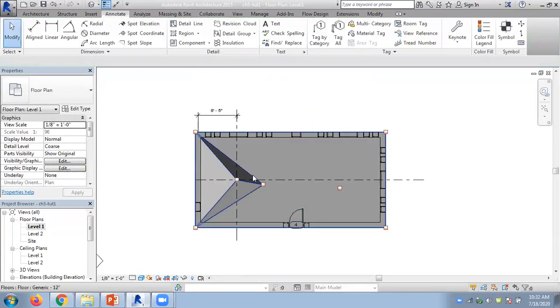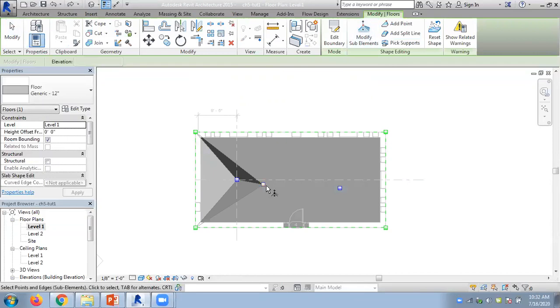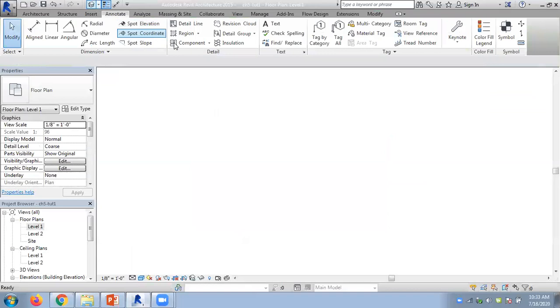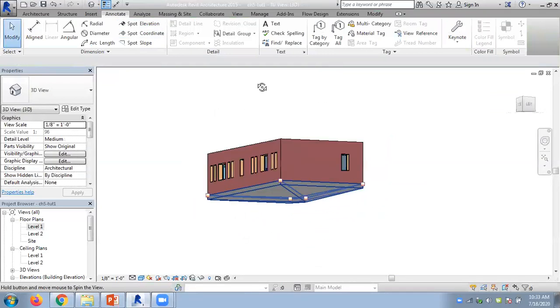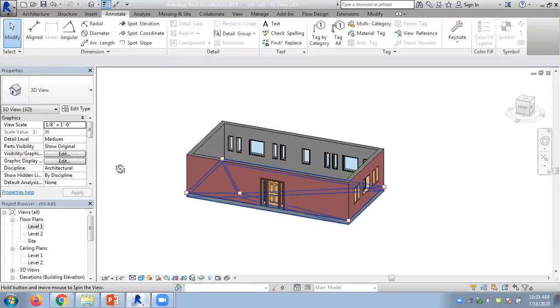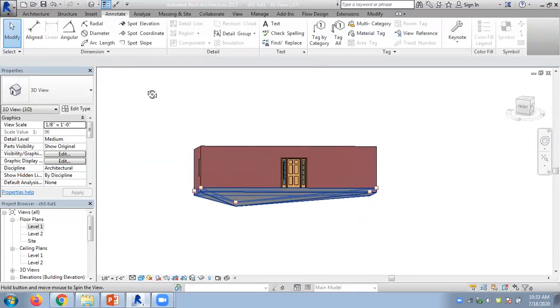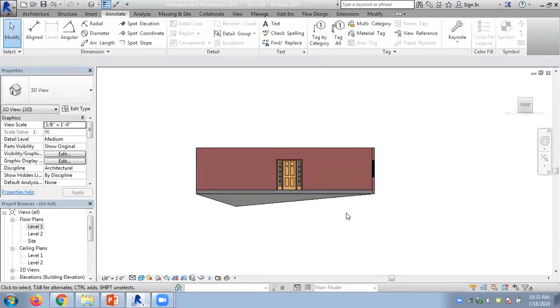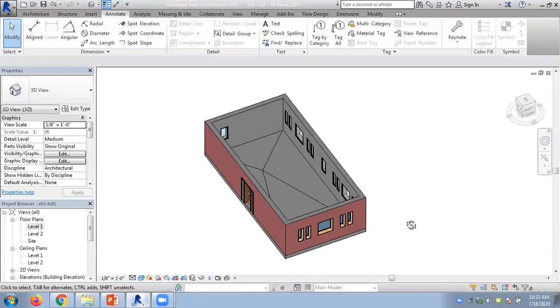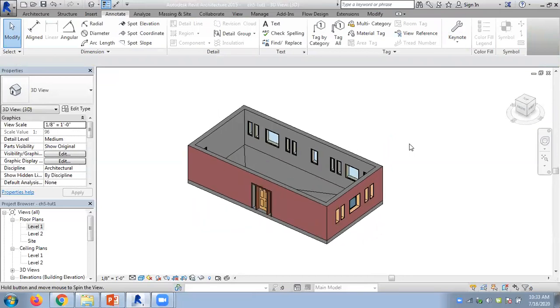sloped down to -3. So if I want to modify sub-elements, click here and we can delete them also. Click here, delete. So only this element is available. Escape. So this is the scenario. So it's now elevated downwards like this. So when you want to design a gutter line or a bathroom drain hole, these kinds of things can be used. Any questions about this?